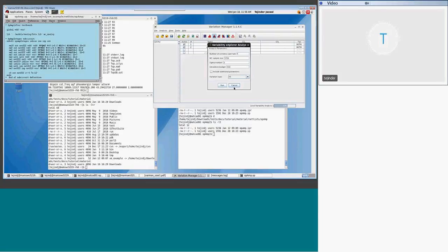Once again, between Variety Explorer and classical Monte Carlo, Monte Carlo will build the whole distribution for you, so you can see it everywhere. It's similar to Monte Carlo, but Variety Explorer will explore more, focusing on details. It's taking care of the distribution, because the critical information is not in the center. Variety Explorer focuses on the tails, doing more simulations on the tails, and if it detects some fails, it will indicate all these extremes of the distribution.